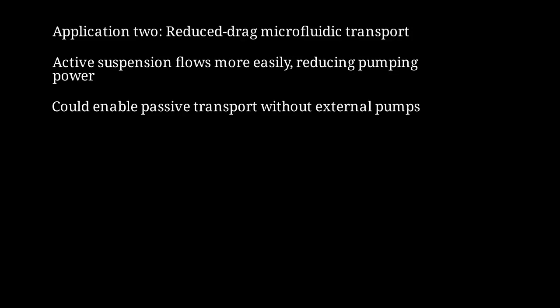An active suspension with reduced effective viscosity flows more easily. You can transport the same volume with lower applied pressure, reducing energy costs. In principle, with strong enough active stirring, fluid could even flow spontaneously without any external pressure gradient, driven purely by the internal active stresses. Third application: self-fluidizing active materials.